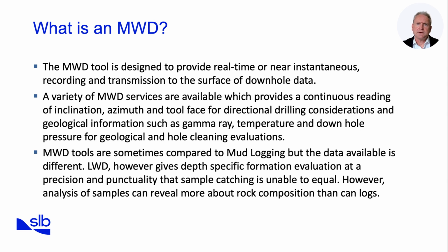When we talk about MWD, or measurement while drilling, we are describing one of the most critical technologies in modern drilling operations. The MWD tool is designed to sit close to the drill bit and continuously gather downhole data. What makes it so powerful is the ability to transmit this information in real time or near real time to the surface. This means that as drilling progresses, the directional team and the geologist can immediately see what's happening downhole rather than waiting until the pipe is pulled out.